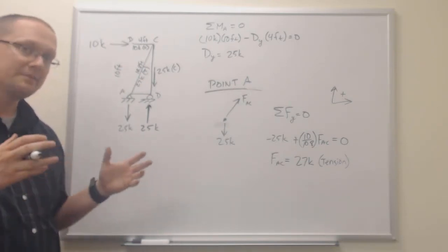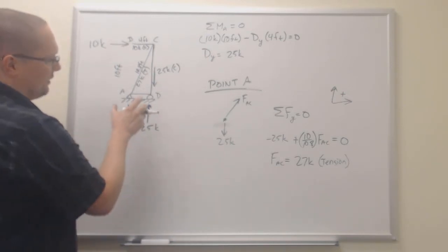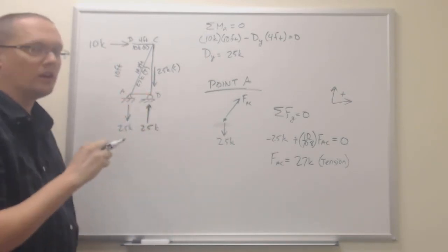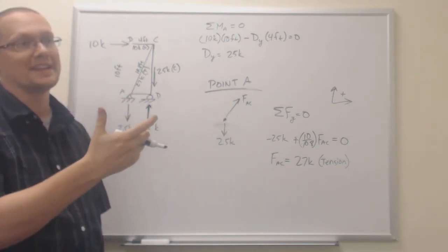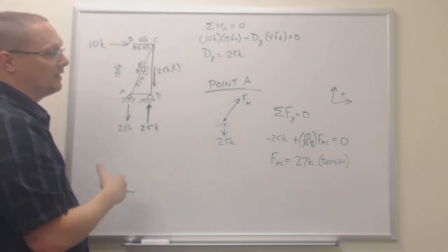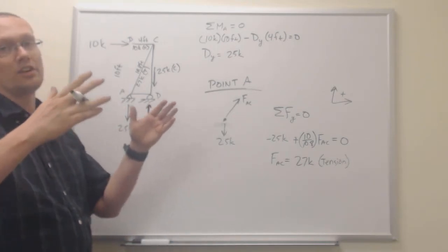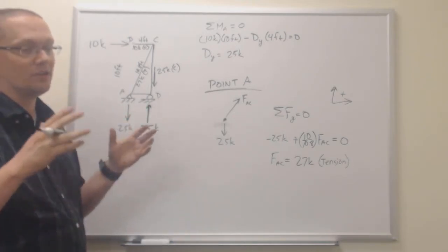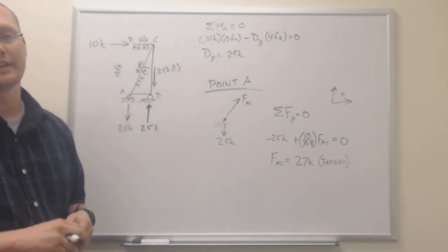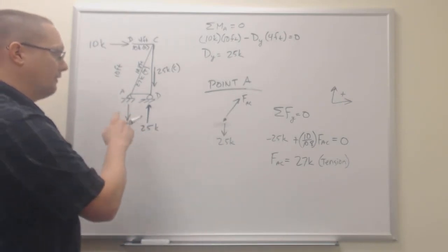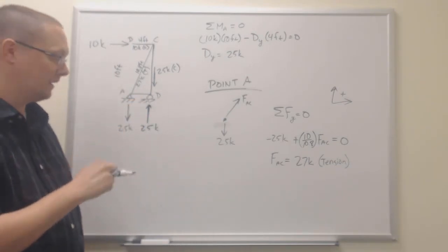So, this is something that's very often overlooked, even with engineers and designers, how the absence of shear wall in buildings dramatically increases the forces that building has to resist. That's why in hurricanes, often the first thing to go is the parts of the house that have the large openings in them, because they don't have as much resistance to shear as other parts of the house as well. So very valuable example there that not a lot of people grasp.